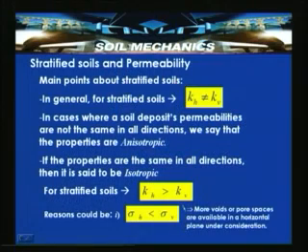As I said, because of the variation of the geostatic stresses, as sigma h is less than sigma v, we can say that it is generally observed that Kh is greater than Kv. The reason can be attributed to, one, sigma h less than sigma v. The other one, in a more detailed way, we can say that more voids or pore spaces are available in the horizontal plane under consideration for the flow to take place. Because of these reasons, we can explain the higher coefficient of permeability in the horizontal direction than in the vertical direction.